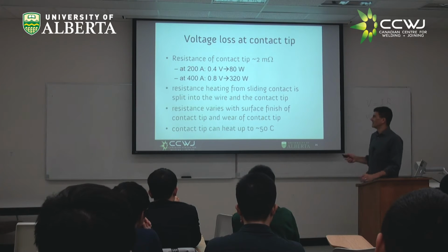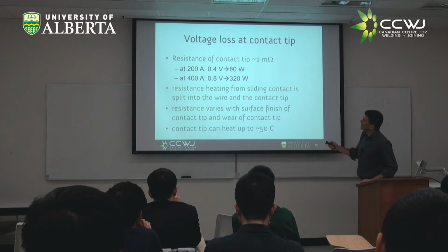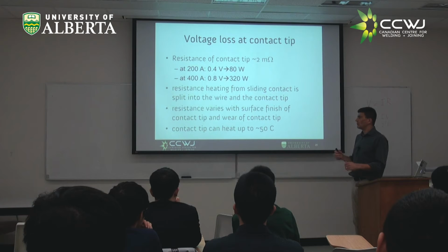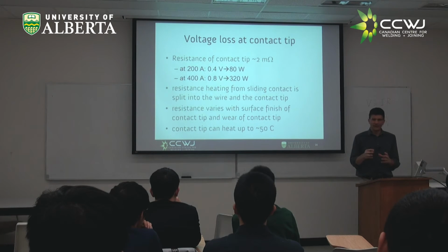And because of these watts generated here, most of those watts go into the wire. I don't know exactly how many. I'm still trying to calculate, but I'm going to assume for now all of them go into the wire. But some also still go to the contact tip. And the contact tip can heat up quite a bit. 50 degrees, that has been measured.